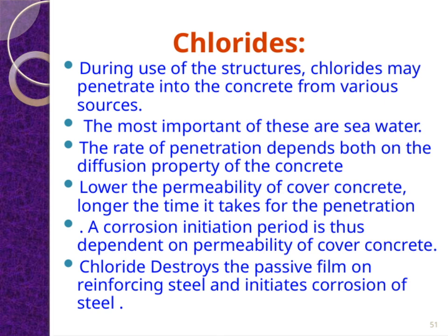During the use of structures, chlorides can penetrate into the concrete from various sources. The most significant of these sources is seawater, which contains a high concentration of chlorides. The rate at which chlorides penetrate depends largely on the diffusion properties of the concrete itself. Specifically, if the cover concrete has lower permeability, it takes longer for chlorides to reach the reinforcement. This means that the initiation period for corrosion is directly influenced by how permeable the cover concrete is.